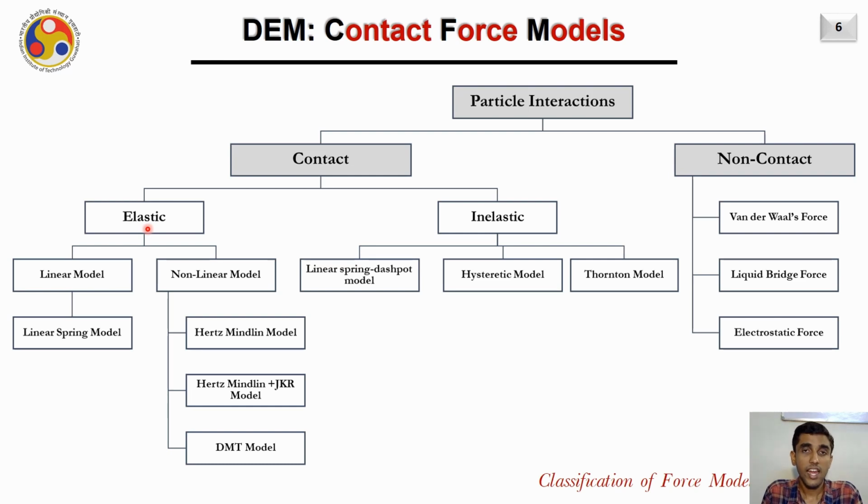The elastic contacts can be based on linear models or non-linear models. In linear models, the contact follows a linear relationship between the force and the displacement, whereas in nonlinear models, the contact force and the displacement follow a nonlinear relationship.